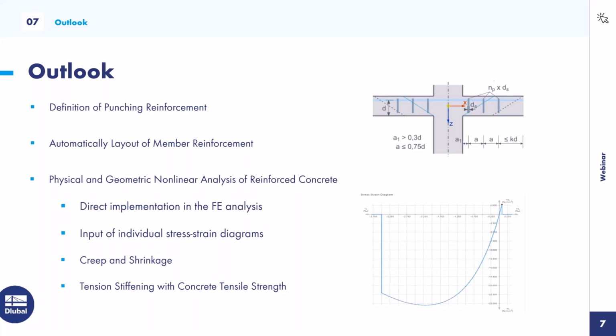So it is possible to use the nonlinearity of reinforced concrete together with other nonlinear materials, or other add-ons like the nonlinear pushover analysis and so on. This is one of the biggest improvements in comparison to RFEM 5, where the nonlinear reinforced concrete calculation was an isolated calculation in the add-on RF-CONCRETE Surfaces or RF-CONCRETE Members, for the participants who already work with RFEM 5.